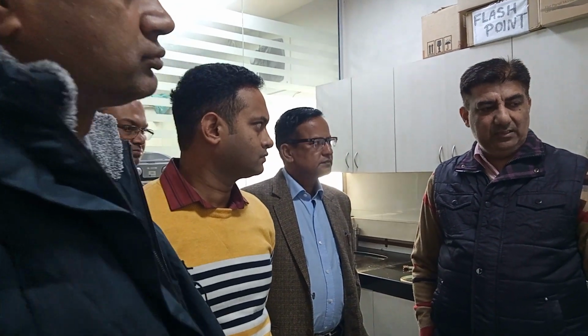Mainly 6 hydrocarbons, and oxygen, nitrogen and hydrogen. The remaining are the hydrocarbon gases. Total 9 gases we are reporting. On the basis of the gas concentration, we can identify the fault that is developing in the transformer. And the other tests that we have the facility for are BDV, temperature, resistivity, water content, IFT (interfacial tension), flash point, sludge, sedimented sludge, then neutralization value.